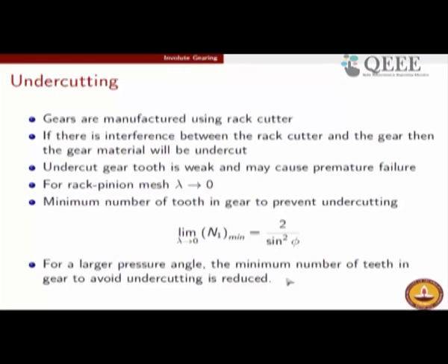But as we said, if you have a large pressure angle, then there is a large amount of wastage in terms of torque transmission, and also it could lead to axial deflection. So you will have to take care of all that and arrive at a compromise value of phi, and all this has been worked out, which is why we say that as per standards the pressure angles are one of those numbers, 20 degree, 25 degree or 14.5 degree.